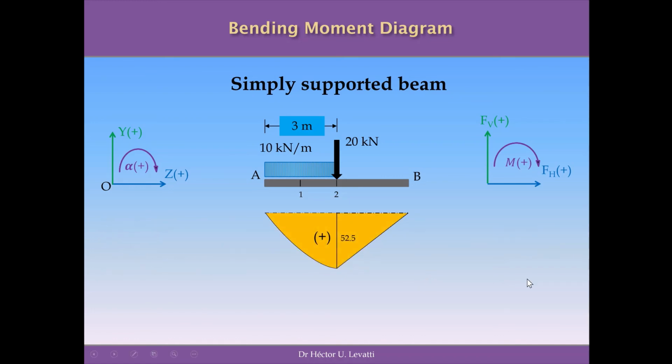So finally, to show a more professional bending moment diagram, this bending moment diagram gives us the distribution of the moments along the whole beam. We did the calculation only in 2 points, in 2 cross sections, and we know 2 more at A and B equal to 0, and after we know that under UDLs the distribution is parabolic, and under the other portion is linear.